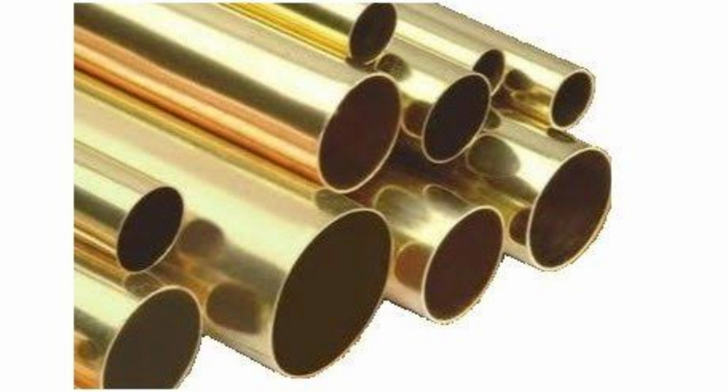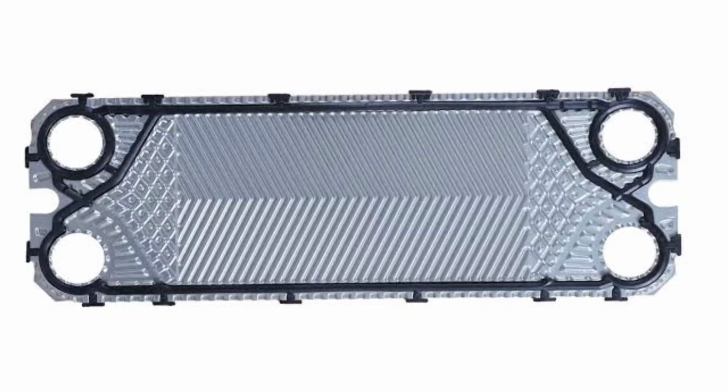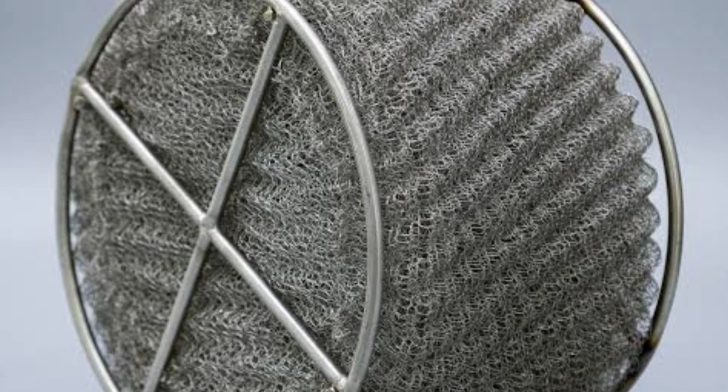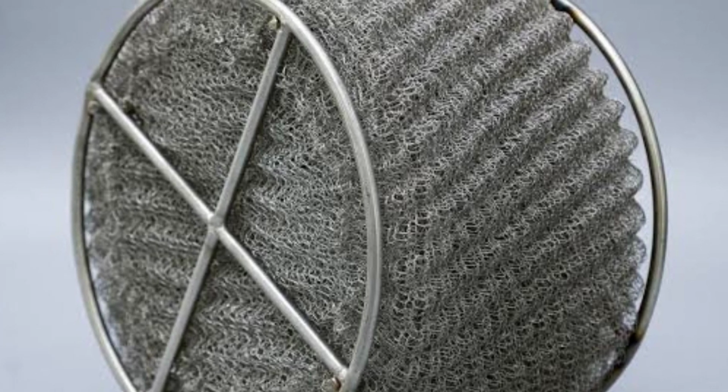Heat exchangers use aluminum brass tubes and Muntz metal tube plate in case of tube type freshwater generator. For plate type, titanium plates are used for condenser and evaporator. Demister is made of layered knitted wire of monel metal.